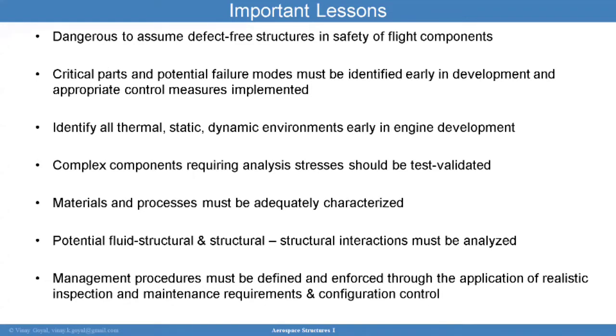Some important lessons learned is that it is dangerous to assume that you're going to have a defect-free structure, especially in the safety of flight components. And the reason that's important is because when you manufacture a part, it's rarely going to be the same as a drawing. And you're going to have flaws in the structure.